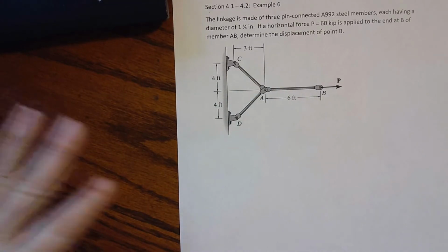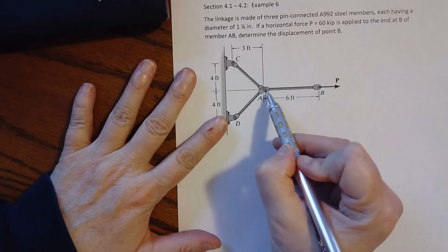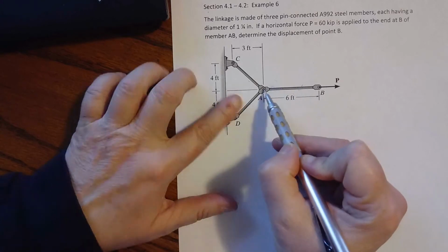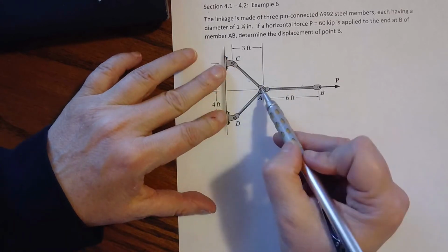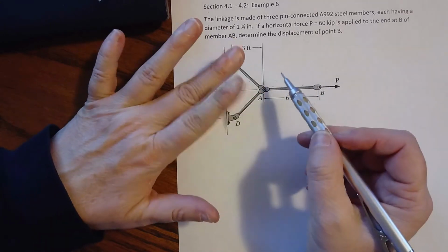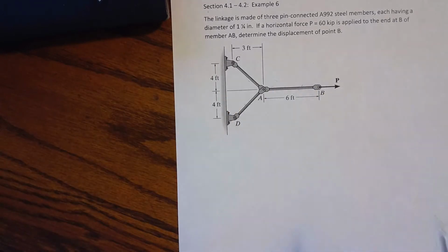So we are going to note that these are all two force members. So I could use method of joints here if I know force P. Okay, so it's got to be equal and opposite. So we're pulling force P here as well. We could use method of joints to figure these out. We can also note that they are symmetric, so I know that they're going to carry the same amount of force as we're moving through.